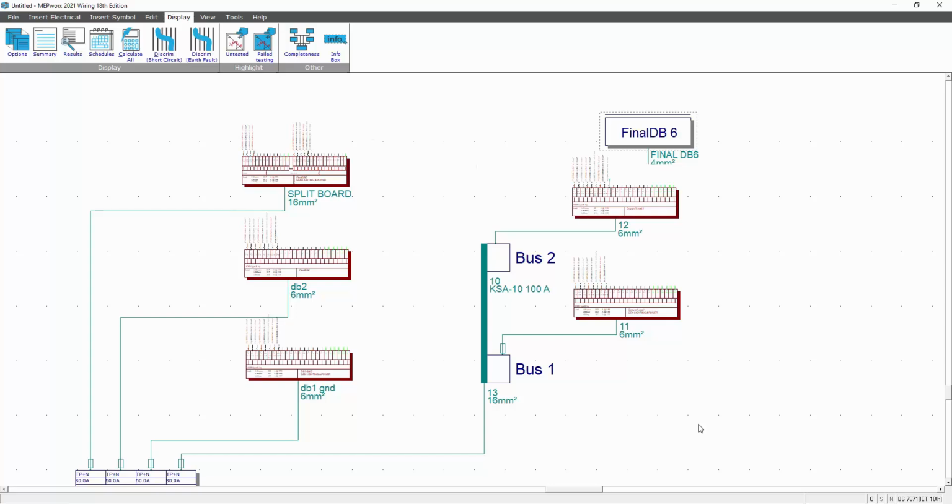And of course, as you build your system up, if you are putting bus bar in upstream, and you are fairly tight on the fault levels on the board, the extra cross-section area of copper might actually increase the fault level, and you could introduce problems with your devices on your final board. So again, always best to sort your problems out at the end of the process.